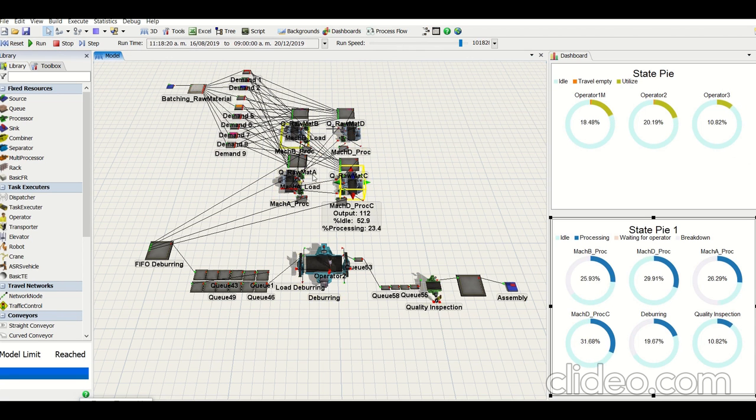We are seeing the operators work within their actual processes, and at the end of this experiment, what we see at first glance is that all 3 processes seem way too underutilized and could cover production in 2 shifts, since each of them individually does not exceed 66%, and neither do the operators.